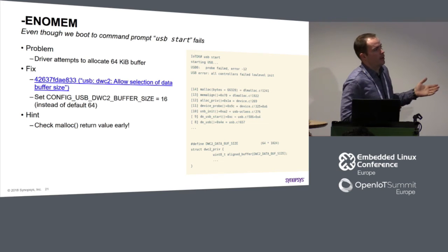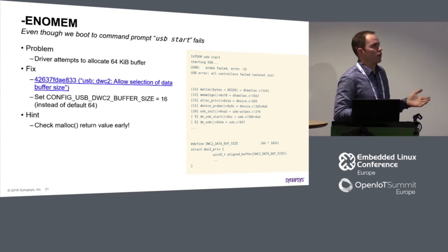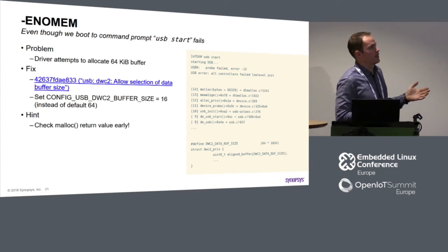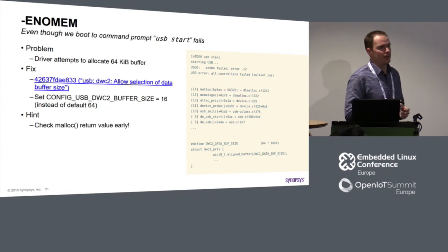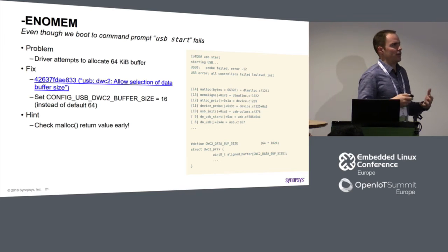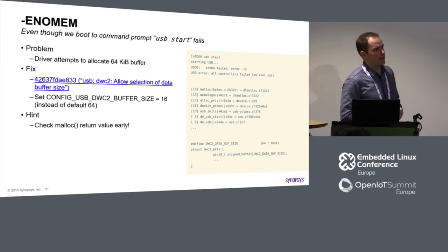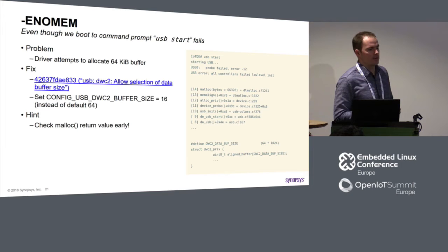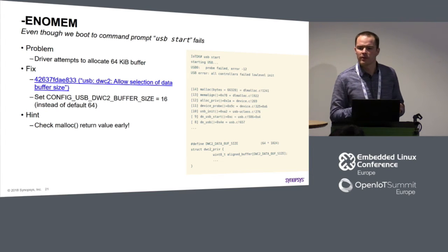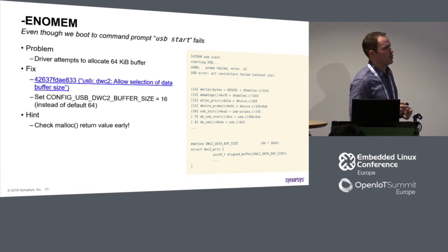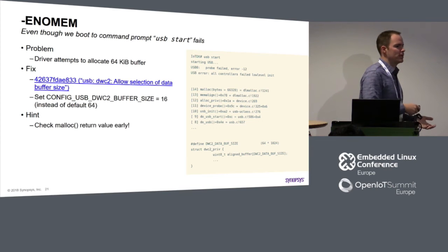What helped here is that I was able to look at the backtrace, and actually some knowledge of how drivers work in modern U-boot. And so this driver is DM, so what is it? Driver model implementation, because if you use the legacy implementation, it will work a little bit differently.